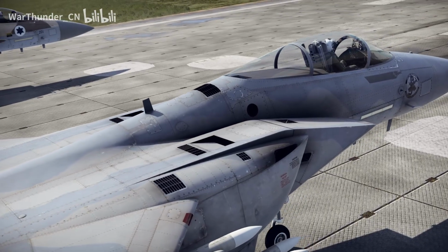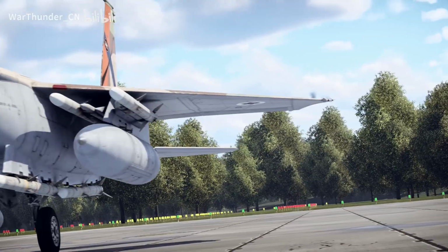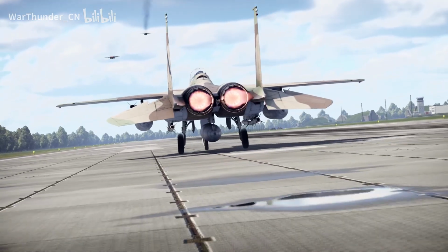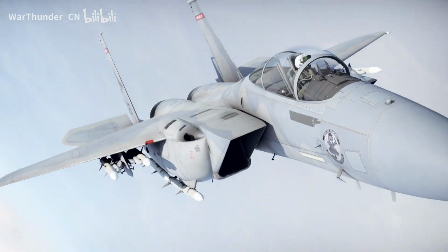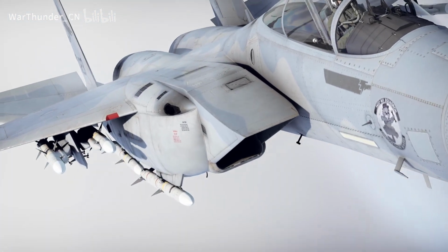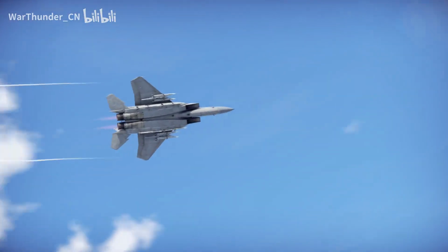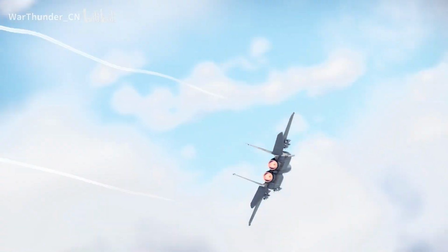On some jets, engineers actively optimize the intake. For example, the F-15's inlet moves depending on angle of attack. As a result, the same engine can behave very differently on different aircraft. In the game, we model the installed thrust, not the static stand value.